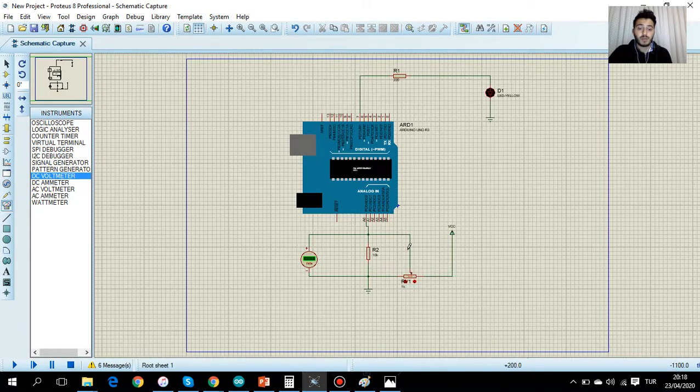When I move the value of the resistor here, the voltage between the second pin and third pin is going to increase or decrease, depending on your resistor. Then, according to my value, I'm going to read it from the analog input, and then I will turn my LED on.